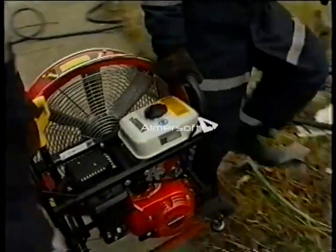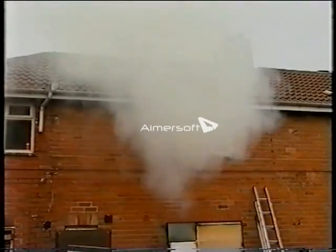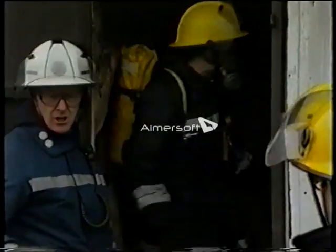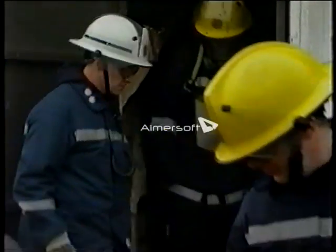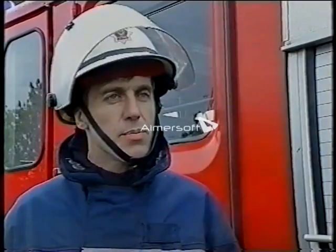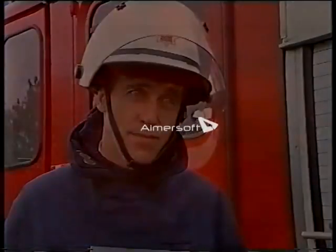PPV enables firefighters to have control over the inlet route for the air, but not necessarily the outlet route, so it may be appropriate for the officer in charge to withdraw teams from the building before using PPV. If things are going to go wrong, they can go wrong more quickly when using forced ventilation. People tend to forget, if things are going wrong, you can always turn the damn thing off.